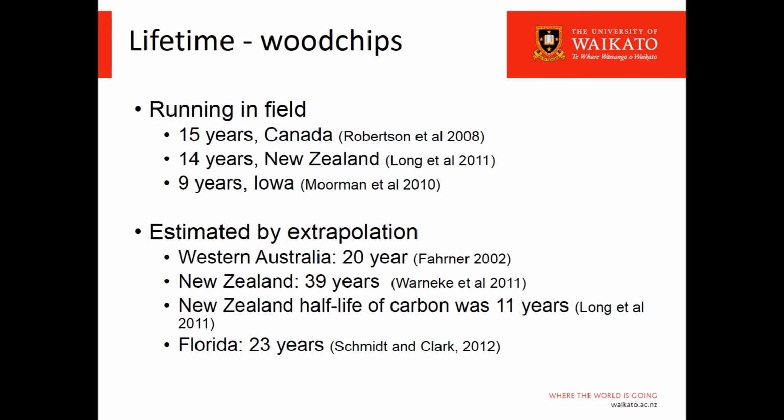How long do they last? We haven't had one run out yet, but what does happen is the rate declines with time. So you might start off at 10 grams per cubic metre per day removal, then it'll go to 5, and then probably to 3, and I think it'll probably stay at 3 or 2 for a long period of time as it just sits there and slowly breaks down and denitrifies. We have a number of different studies that have looked at these kinds of lengths, but at least 10 years, and then possibly longer than that. And then you can just put more in if you want.